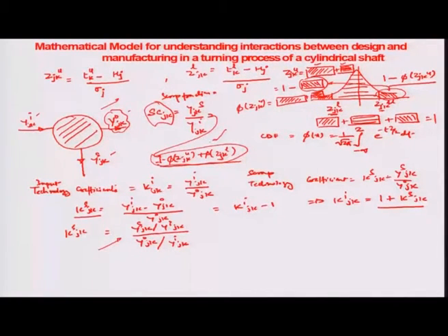So, without doing any real experiments again, if I knew just what is going to be the process mean and the standard deviation, and also what is going to be the tolerance, I should be able from a normal table to just glance and look at this particular value, which is percentage reject. So, let us calculate this in a little better manner.